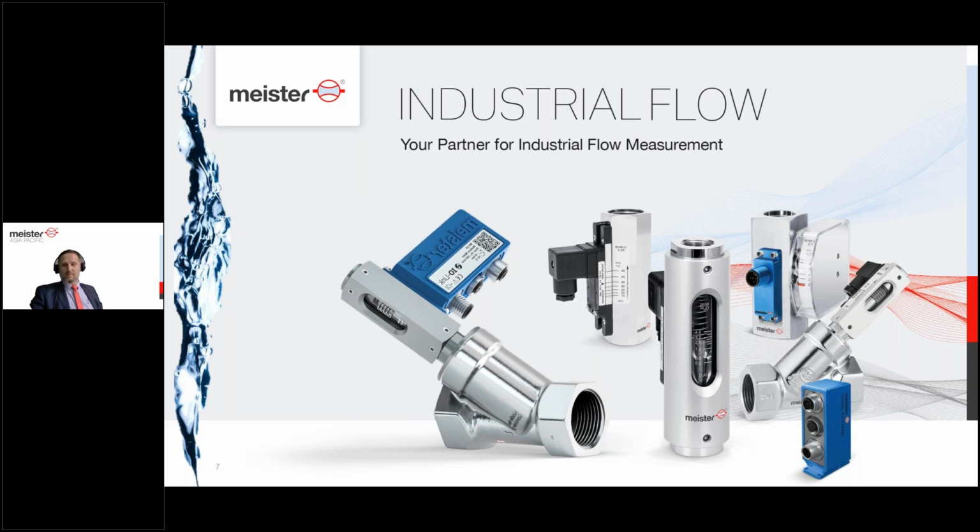We do see in this picture that it's possible to have a switch contact, which customers can adjust easily, and every mechanic can set that set point by themselves with a screwdriver. No special training required, I believe. There can be one switch contact, there can be two switch contacts at the same time on one flow meter, one measuring a minimum flow level, another switch contact measuring a maximum flow level maybe. If you wish, you could even make a third switch contact.